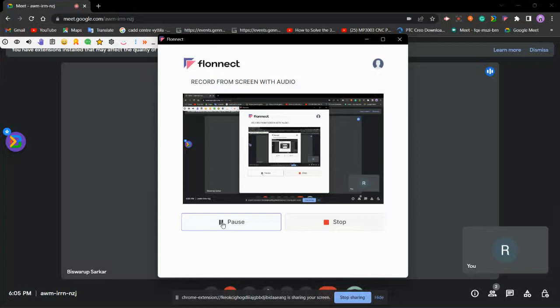Then I'm selecting this plane, giving a sketch, drawing a small circle here. For the time being, I am not fully defining that, and giving a pad here. Also, one thing you see, we can directly go to pad and draw the sketch. I will show. I'm going to pad, and under the profile selection, there is a sketch icon. Can you see that?